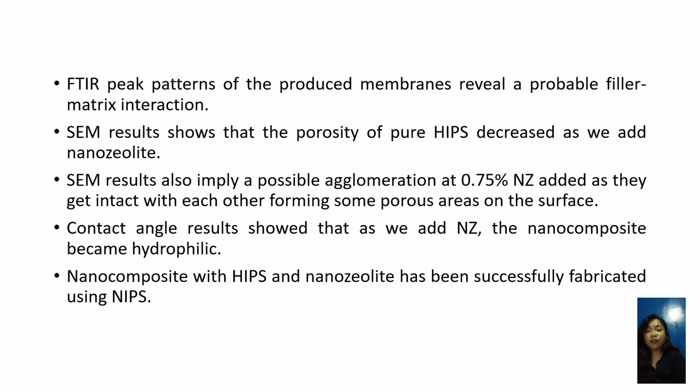Nanozeolite helps with the entrapment of solvent molecules, so HIPS can have time to assemble because of the gradual evaporation of the solvent. SEM also implies a possible agglomeration at 0.75% nanozeolite added as the particles get intact with each other, forming some porous areas on the surface.